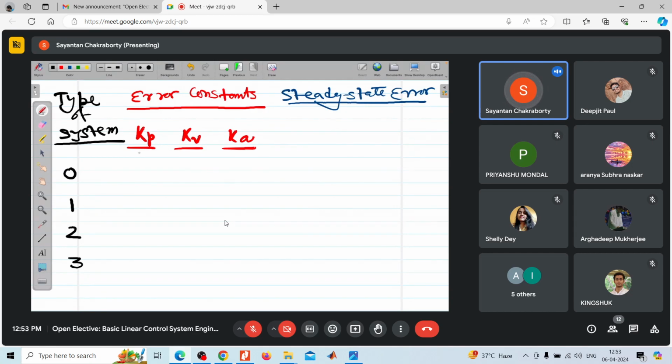Like peak time, settling time, peak overshoot, rise time, the performance indices. And these are defined only for second order systems, right? For third and fourth order systems, you cannot have these things. So to quantify those systems, one of the methods is to represent the third or fourth order system by a second order model. Model order reduction. The most common form of this approximation involves the concept of dominant poles.